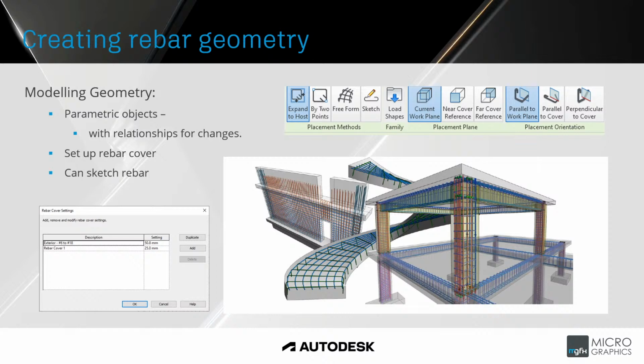You'll see there on the top right of the screen, there's some ways to draw the placing of the rebar. One of them is a sketch, where you can simply in a section or an elevation start sketching your shape or your bars, and Revit will actually recognize what you are doing and define a shape code to that if there is a shape library loaded.